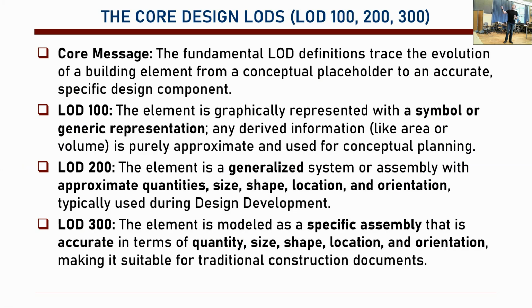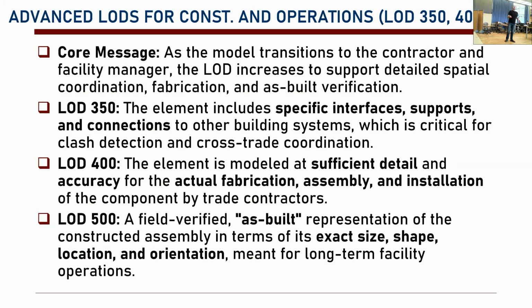Then we have advanced LODs. So these were core design LODs. Okay? But advanced LODs are for construction and operation. We have LOD 350. Basically, from contractor to facility manager. So the contractor needs detailed models for the construction process. Okay, for the building construction process. The facilities manager needs the model for facility management operation. So as the model transitions to the contractor and facility manager, LOD increases. The details that we include increase to support spatial coordination, fabrication, as-built verification.